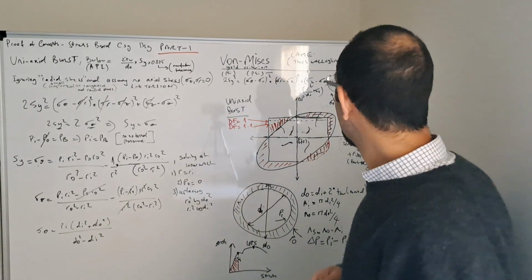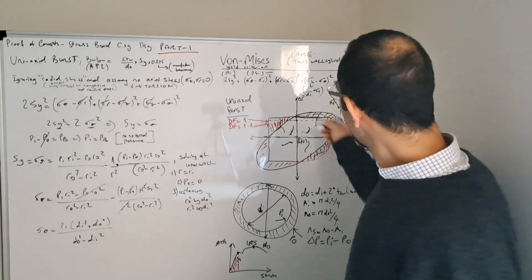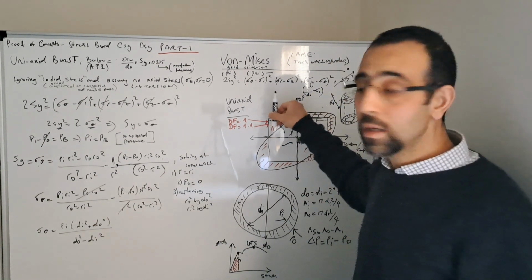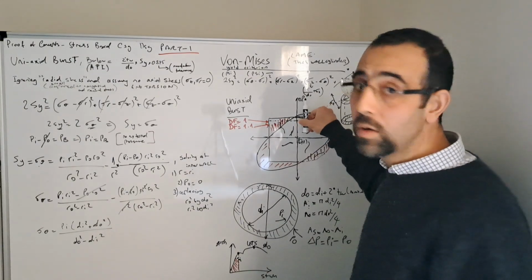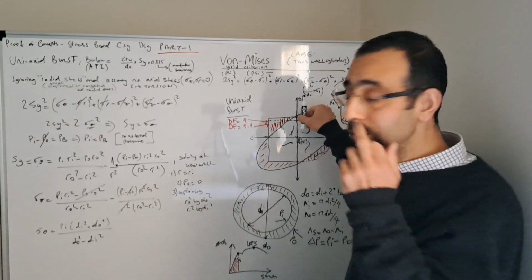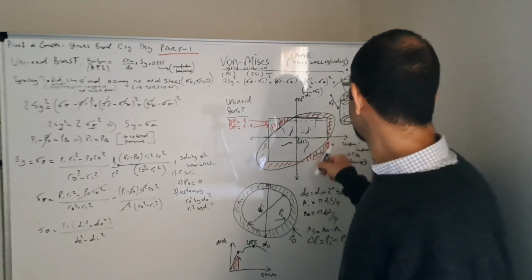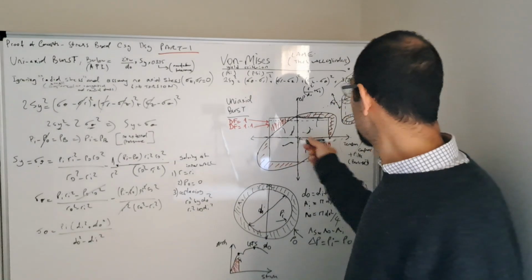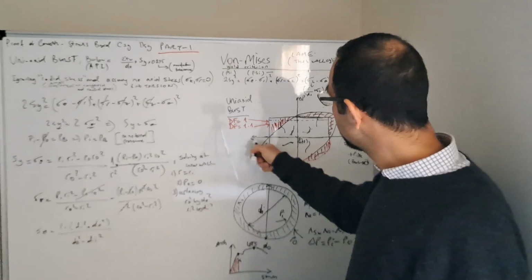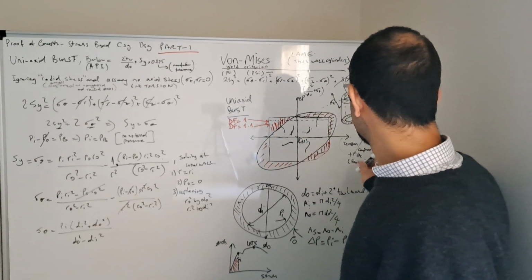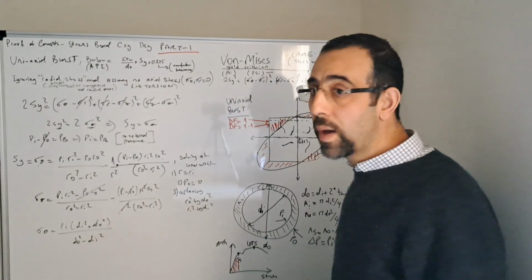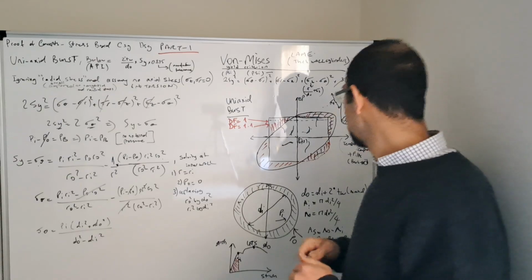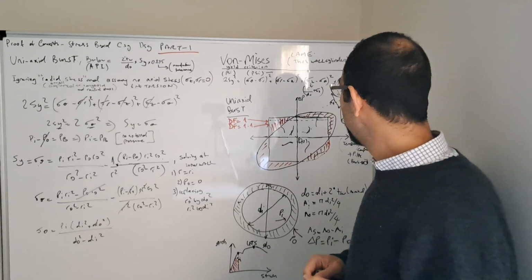So when we look at the axes of this design limit, the y-axis is the delta P, that's P internal minus P external, and the x-axis is tension or compression depending on the load state. So this side is the tension, this side is the compression, plus the backup pressure, which we are going to look at a bit deeper in part number 4.